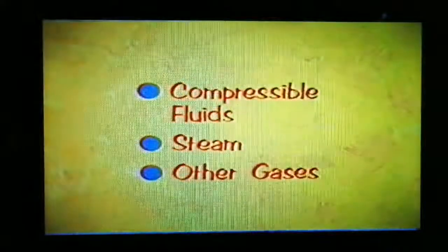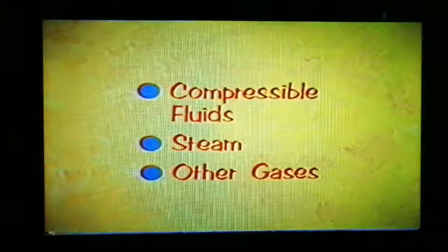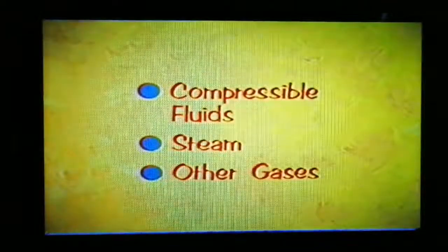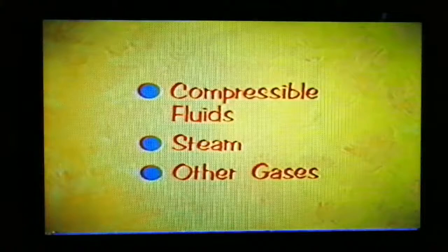Safety valves are used for compressible fluids, such as steam and other gases. This compressibility demands rapid overpressure relief. Safety valves have pop seats and plugs which open rapidly on overpressure, relieving at full flow.